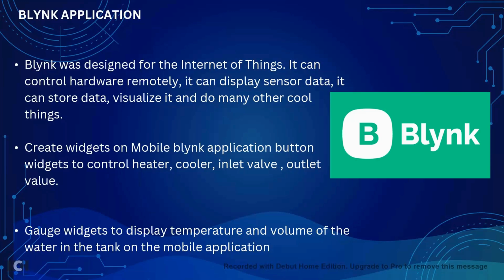Create widgets on the mobile Blink application: button widgets to control the heater, cooler, inlet valve, and outlet valve, and gauge widgets to display the temperature and volume of the water in the tank on the mobile application.